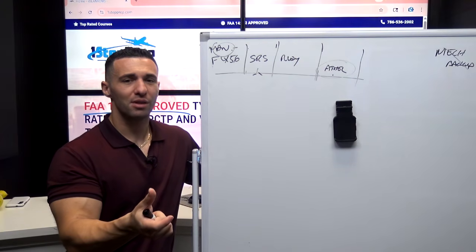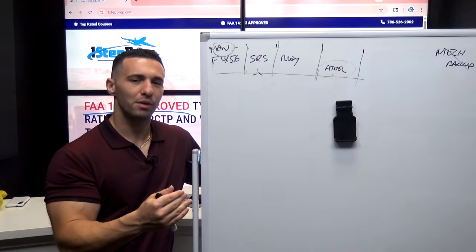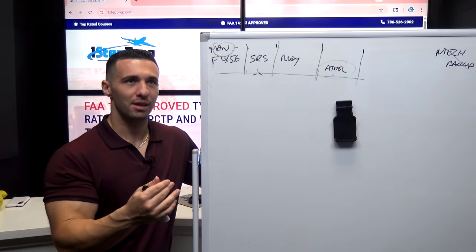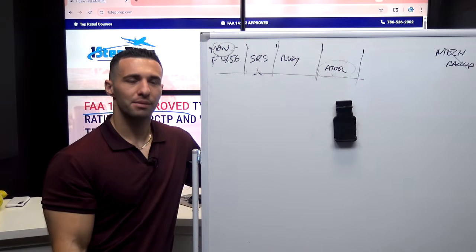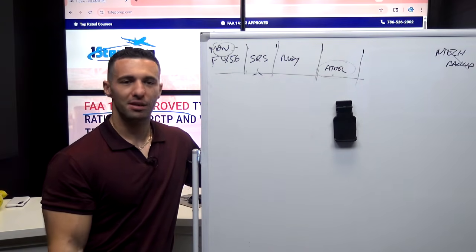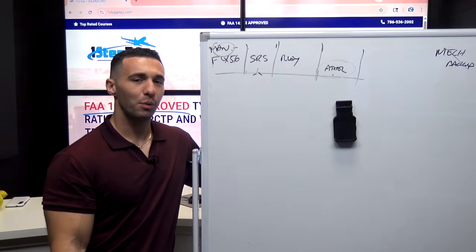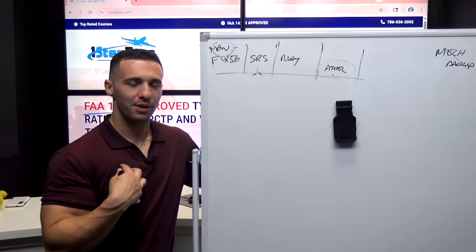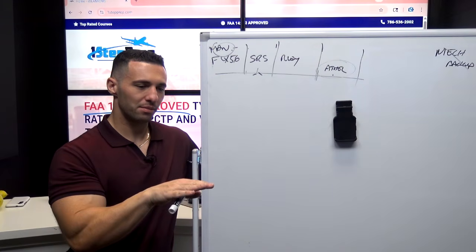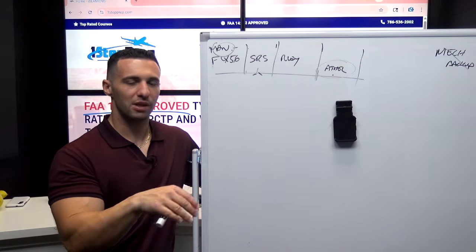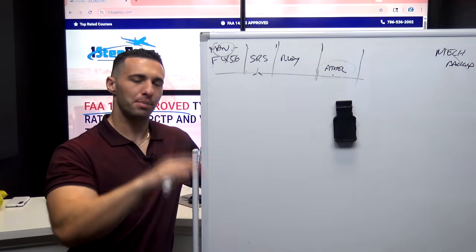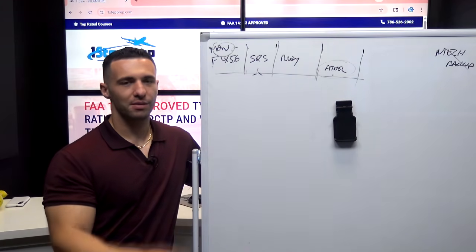It's pretty close. Could you technically go below that maneuvering speed of S speed down to 170? Yeah, sure. No problem. It's been done. People do it. It's not a problem. At least personally what I do, if I start slowing below that ideal speed for the configuration, I'm mainly just looking at my pitch angle and how far away the VLS is.